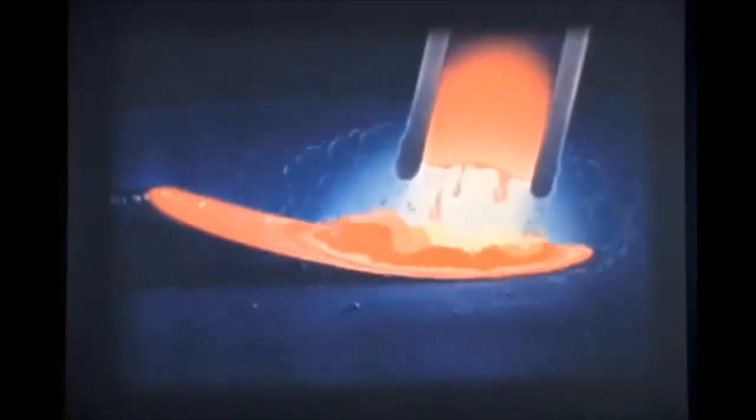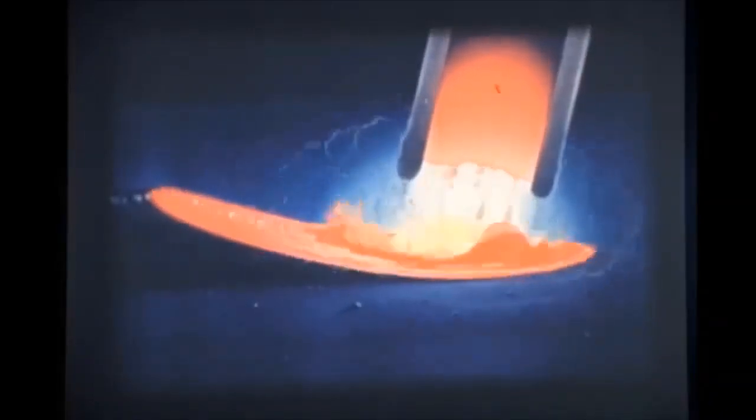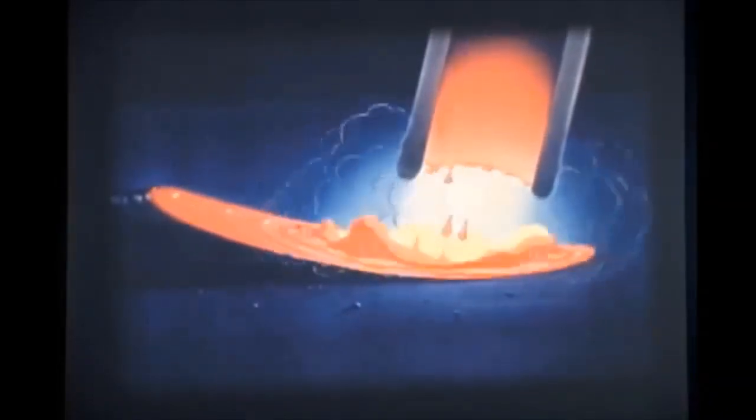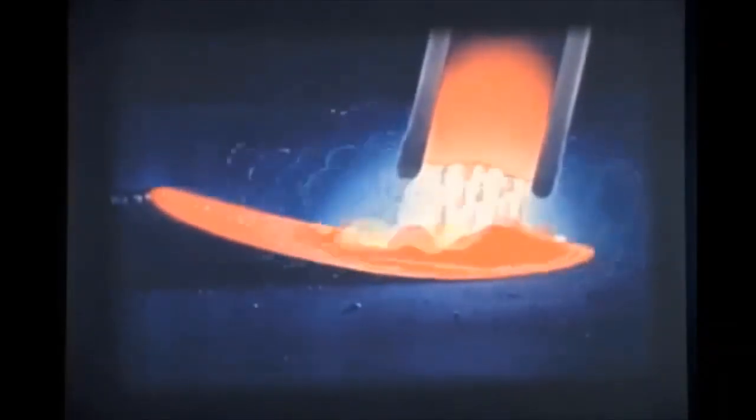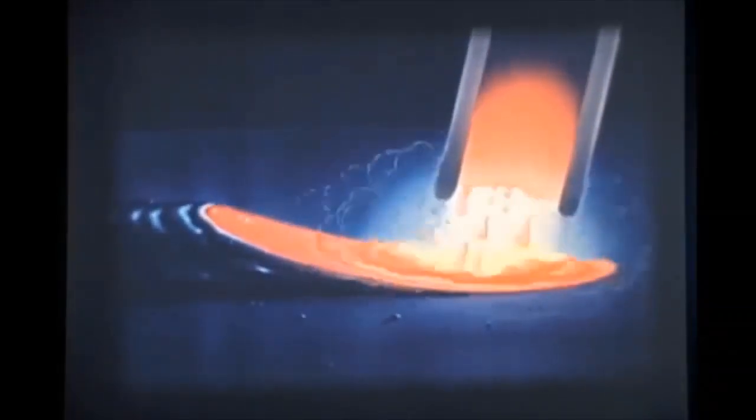A gas is formed, covering the arc with a protective shield that prevents the exposure of the molten metal to the air and therefore prevents the formation of harmful oxides and nitrides in the deposit. Also from the coating, chemicals acting as cleansing agents enter into the metal to help to remove the impurities. These chemicals with the impurities float to the top and, cooling, form a coating or slag over the bead.